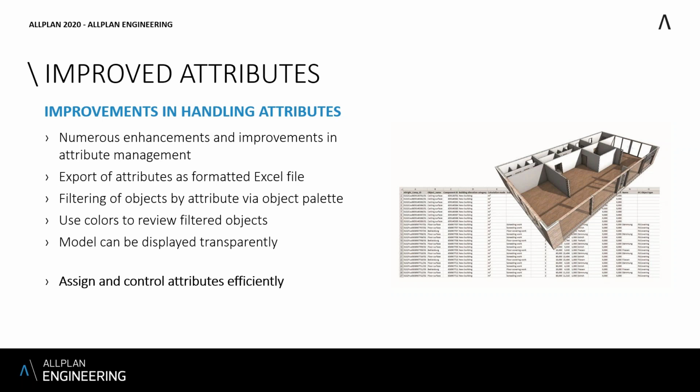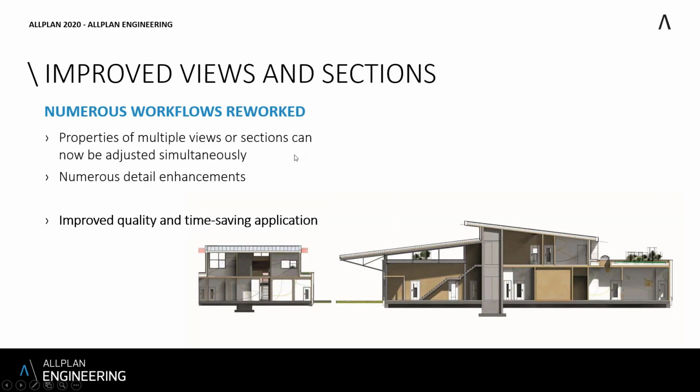If you just install a plugin, it's a BIM Plus for Excel. In Excel you find a new add-on tab, and you connect to BIM Plus. You download the model, the IFC model. You import all the data of the model, start making changes, and then it synchronizes both in BIM Plus, in the cloud platform, and in the software. This helps a lot, because for many third parties it's easier just to handle attributes and information through Excel. So this is something they innovated.